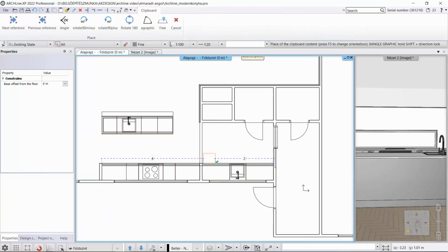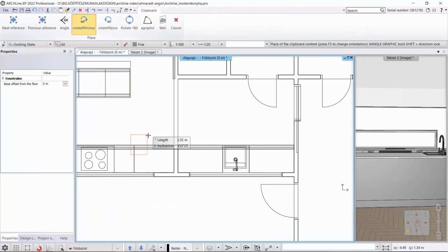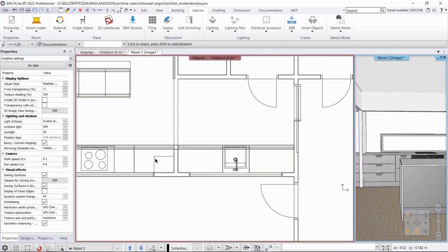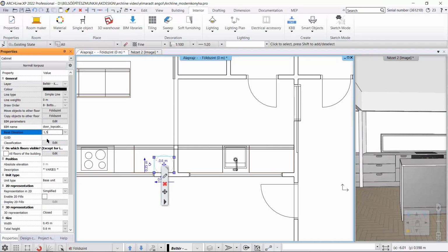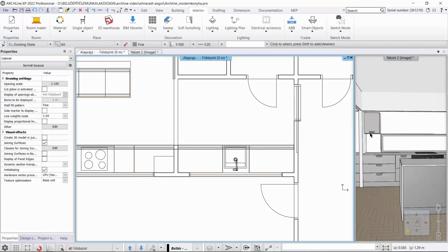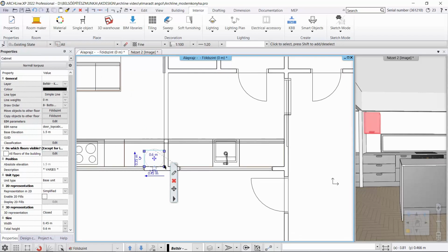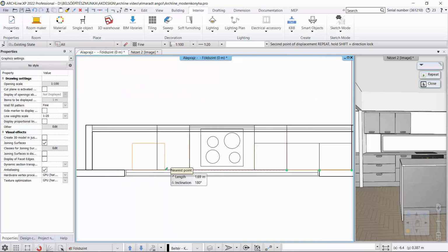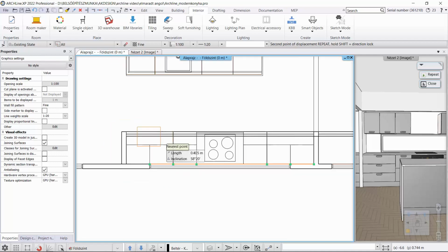Then we place it on the floor plan and adjust it in place. Its relative height is 0, this must be rewritten to 1500 mm. Then we put two more elements next to each other by copying and moving. Leave 900 mm for the extractor fan. Then there are 3 pieces 440 mm upper cabinet elements.